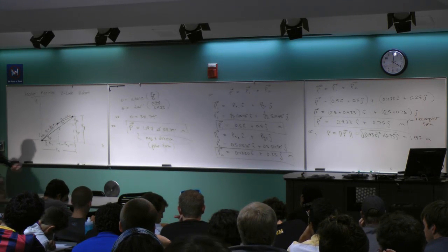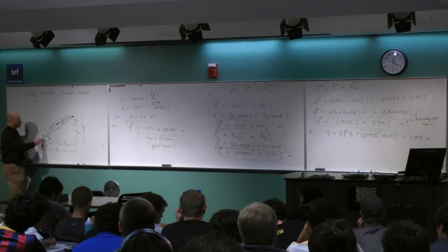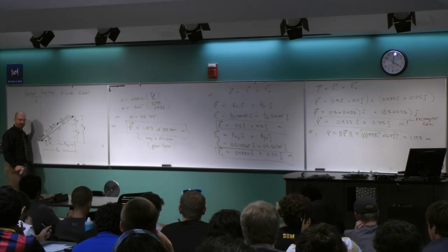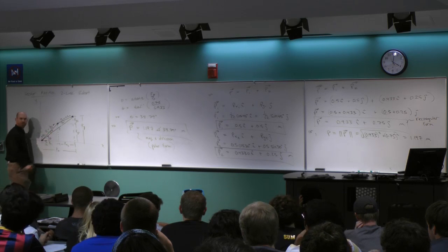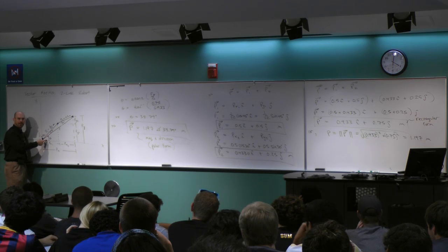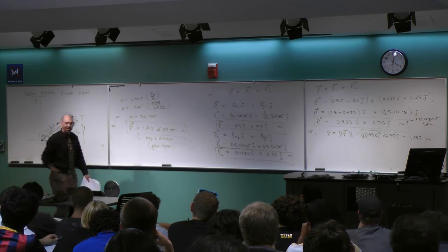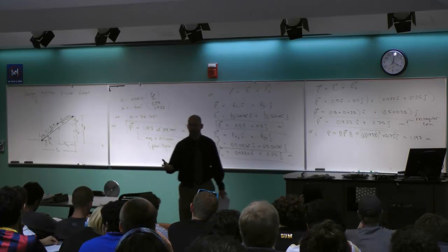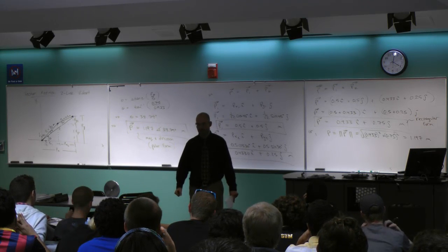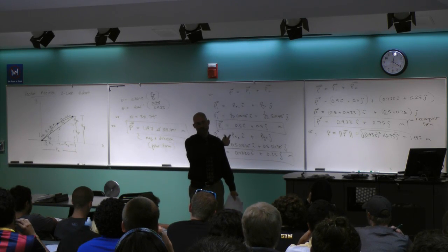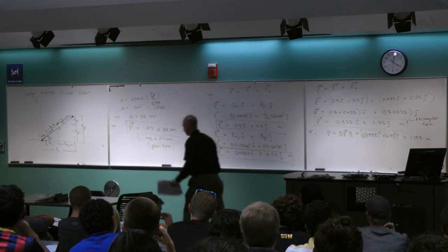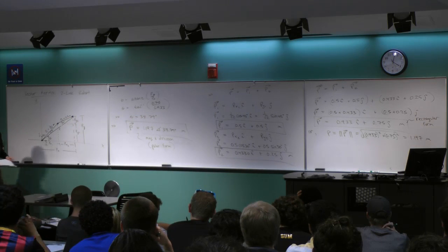So keep in mind, if we didn't use vectors here, and we just drew the two-link robot and asked the question, what's p and what's theta? In order to do that, I'd have to find this guy, alpha, right? Because I know that's 45. And if I had the alpha, then I could subtract from 90 to get the theta. So this entire business of the laws of sines and cosines and all the stuff we did before, we'd have to do all that if we didn't have this vector tool. Now that we've got the vector tool, I can just look at it and go, I'm not using laws of sines and cosines. I'm just going to do some algebra, and bam, the answer just pops out like magic. So it's pretty powerful for that kind of stuff.